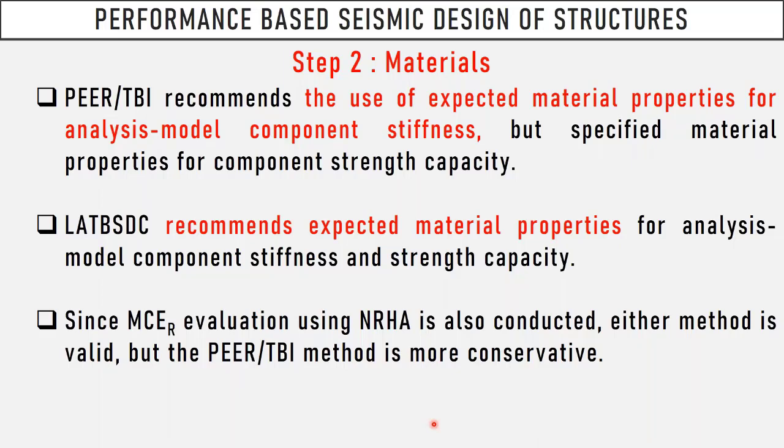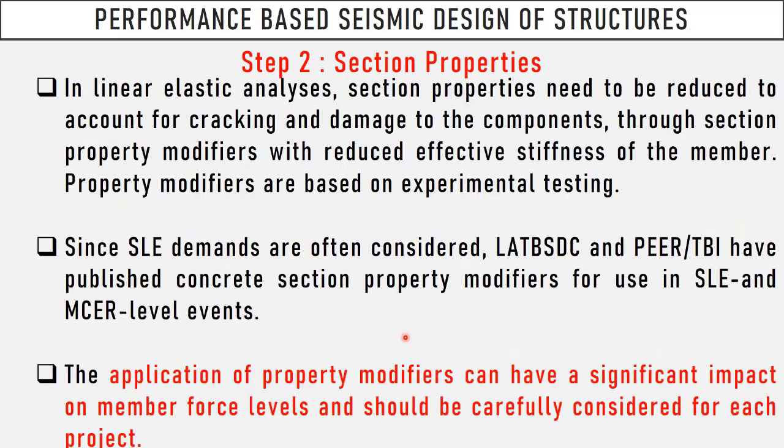after all these linear analyses, we are going to come up with a design, a so-called preliminary design, and we are going to evaluate everything with nonlinear response history analysis. It's a kind of verification process. And of course, section properties are a very critical parameter to be decided. Application of these property modifiers has a significant effect on the member forces and deformations, of course, and engineers should be very careful which one to use.